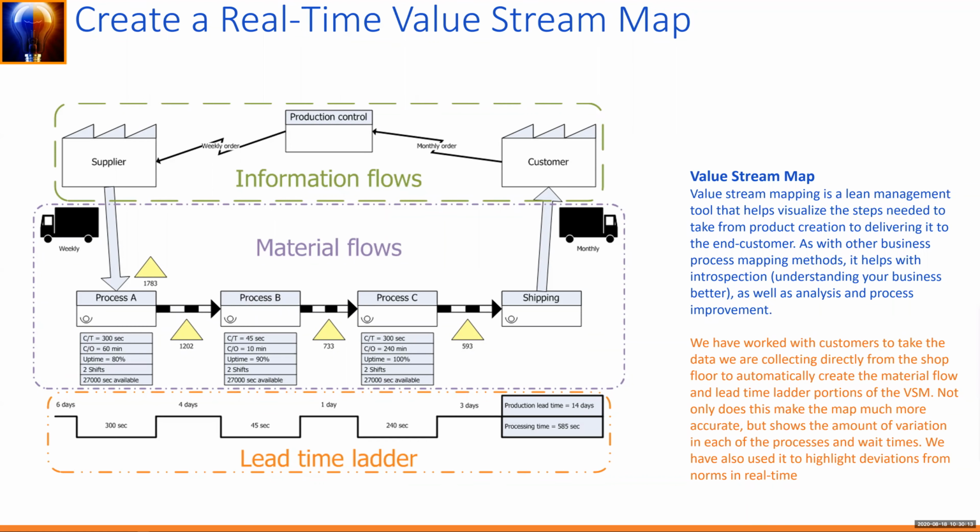And if you think about the different systems that you're putting in place, an OEE system actually comes pretty close to having this data, but you can get all of it with an IIoT system. And especially if you're tracking work order numbers as well as part numbers and so forth, you have the capability of looking even across sub-assemblies to parent assemblies and so forth that will allow you to say, for this given item, what are all the steps that I typically run in this process historically?